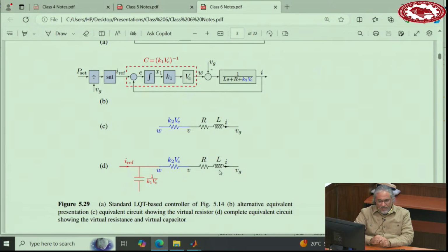And vice versa. If a load in this grid disconnects, the voltage tends to go up, then the voltage across this line tends to go up, and the capacitor voltage tends to go up. The capacitor absorbs energy. So it's a stabilizing behavior. Got it? Very similar to what we got in the synchronous machine. So this control that we have here is like adding inertia. However, the problem is this one.